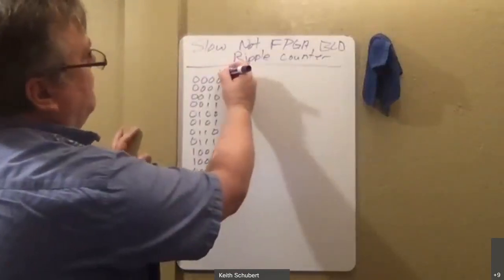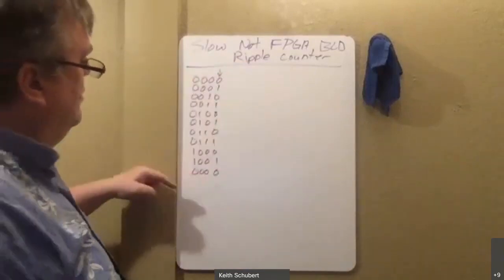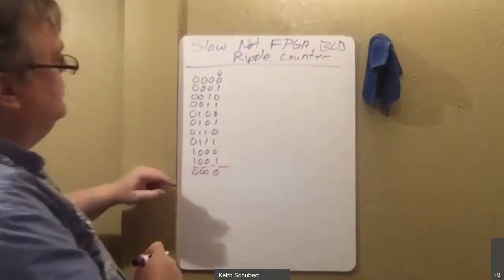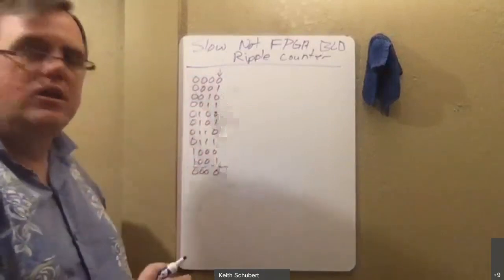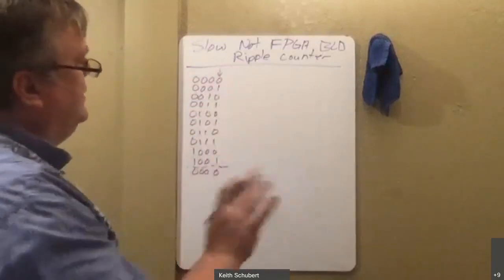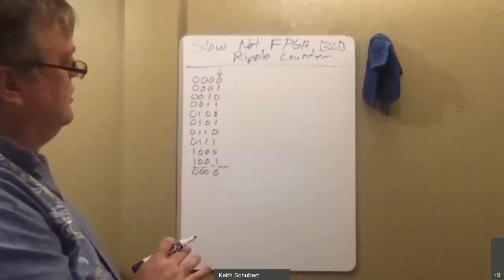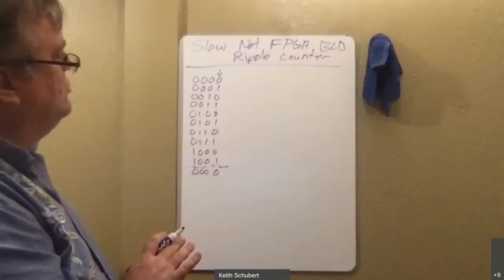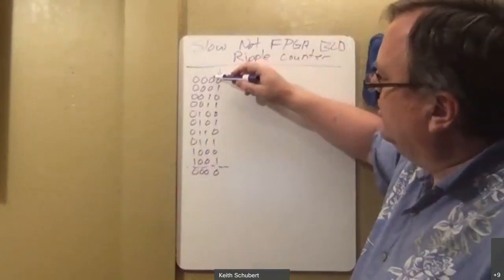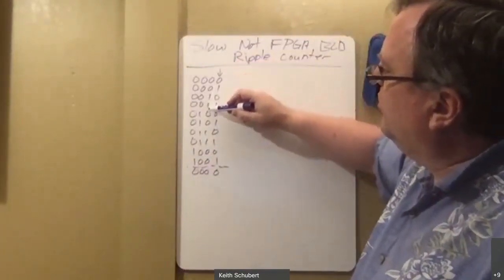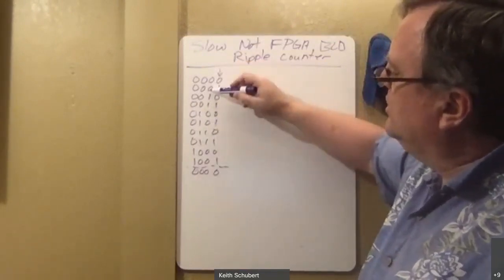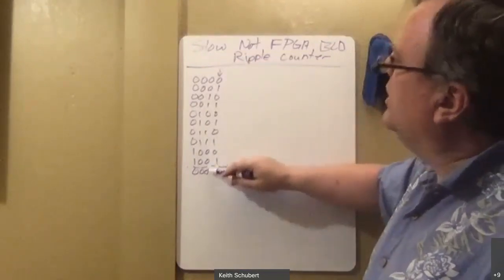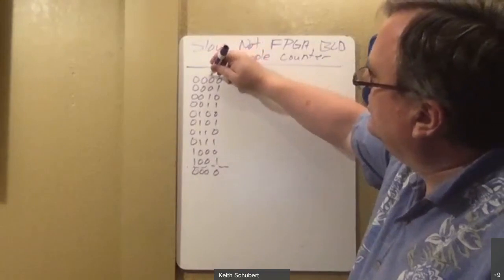First off, if you just look at the least significant bit, this is kind of the end of the normal sequence here. But it does that nice 0, 1, 0, 1, 0, 1, 0, 1, 0, 1. So this is toggling exactly when you would expect it to toggle. There's no strangeness to its pattern at all. If you look at the next one that's in here, I've got my zeros, my ones, zeros, ones, zeros, zeros. So it does something weird here.